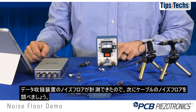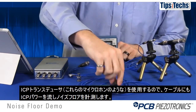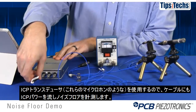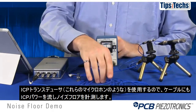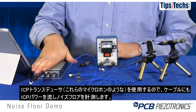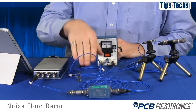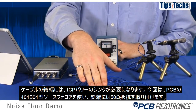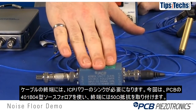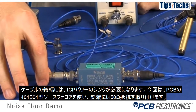The next thing we want to do is define the noise floor of our cables. If we're going to power an ICP transducer, like these microphones over here, we want to actually send that ICP power down the cable when we measure the noise floor of the cable. So at the end of the cable, we need some sort of sink for that ICP power. In this case, we're going to use the PCB 401B04 source follower, and we have a 50 ohm terminator on the end of that.